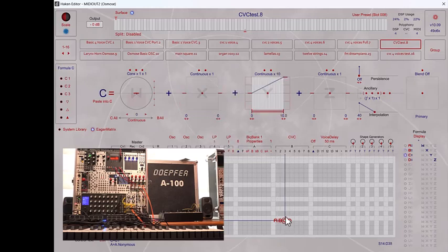Now C is going to be aftertouch. I set this to go from 0 to 10 volts. If I turn up my Y that I had before, there I've imposed that modulation. You can hear Y coming in. If I take Y down to a smaller value now, you can hear that range of modulation is a lot less. So Y is going to be configurable to your needs here based on what you need to do voltage-wise.